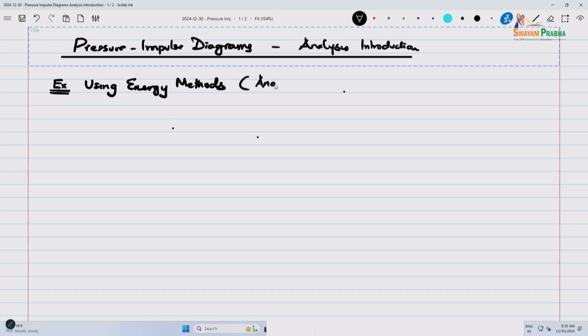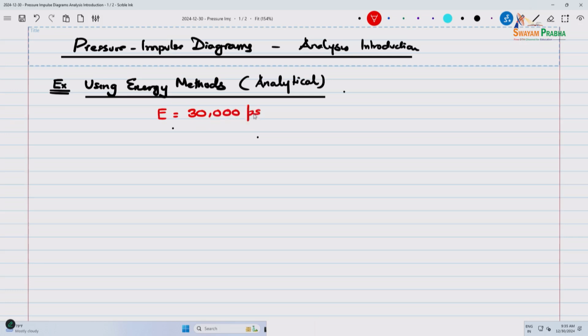And these are analytical expressions. I'm presenting a lot of analytical expressions because those are always what gives us some answers if we do advanced finite element analysis. So here you're given E. Again, just be consistent in the units, and you don't need to convert back. One recommendation I have for conversion, what I do when I use SI, is finish everything in the units I am most comfortable with and then convert final values, answers alone. This way I'm able to judge the results.